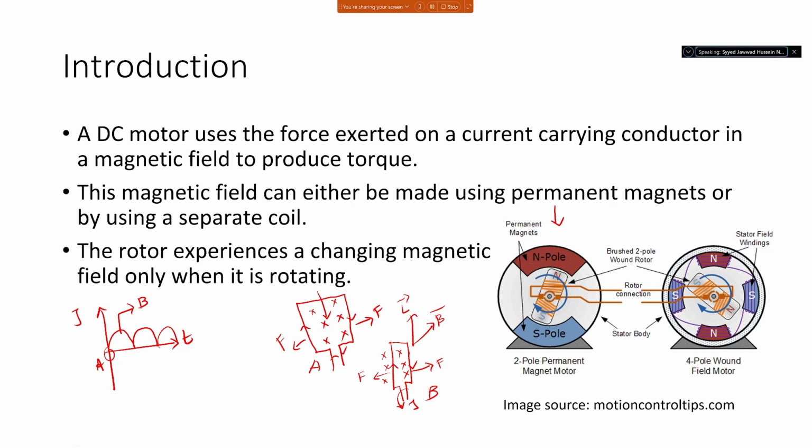So this is one separate coil winding. There's a rotor connection. Nothing changes there. But I replace the north pole with one coil, and the south pole with another coil which is taking current in the opposite direction. So this has field lines going like that, and that has field lines going like this. So it's acting as an effective north pole and an effective south pole, and that becomes the external magnetic field.